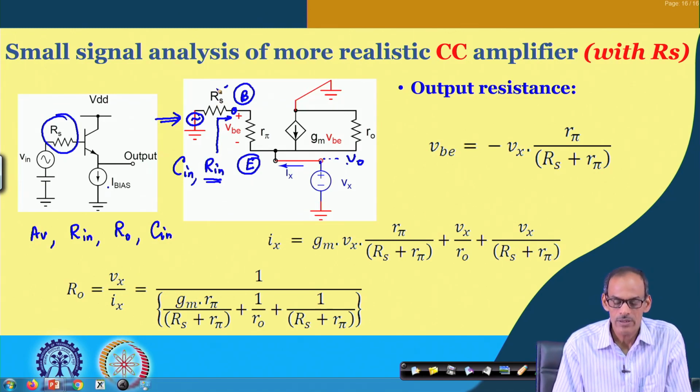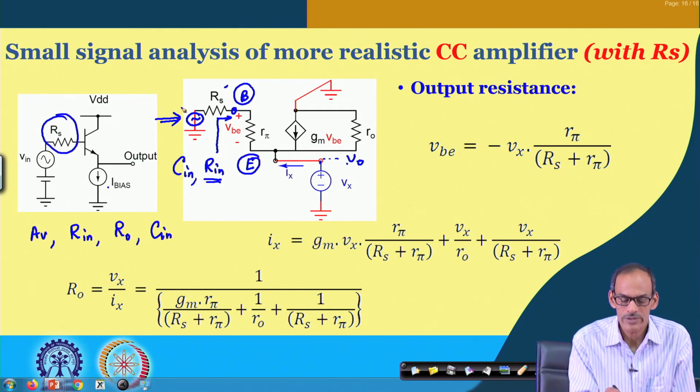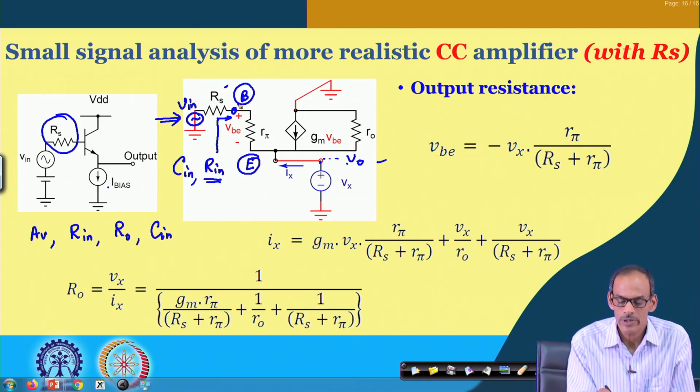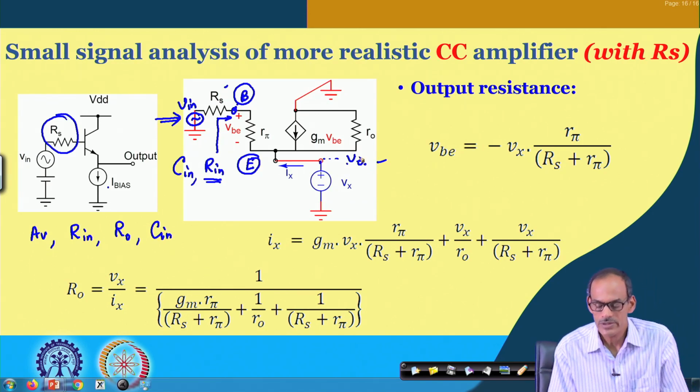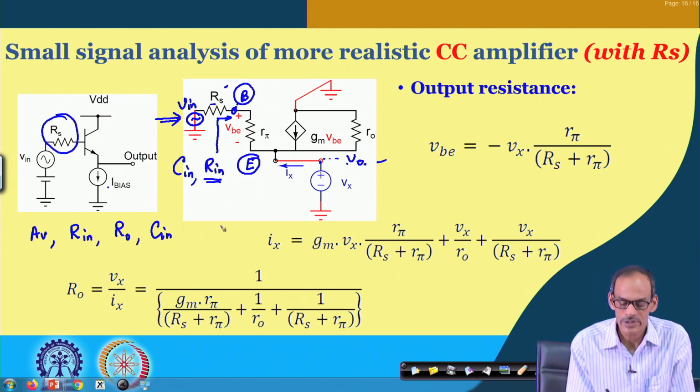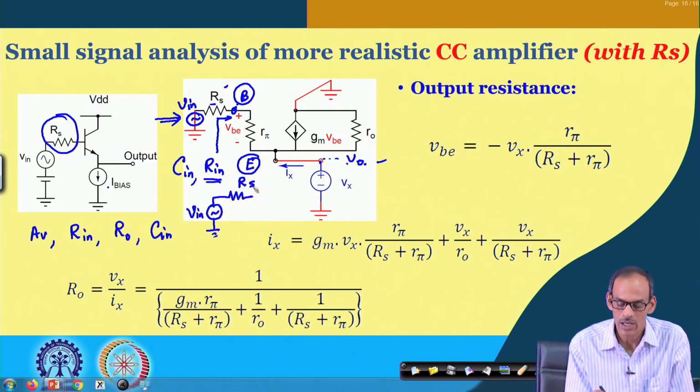And the voltage gain, if I consider this is the primary input and this is the corresponding primary output, from base to emitter terminal, the gain remains the same, namely close to 1. Only difference is that if I consider R s, I do have V in here, and then we are applying the signal through this source resistance R s to the effective input resistance.